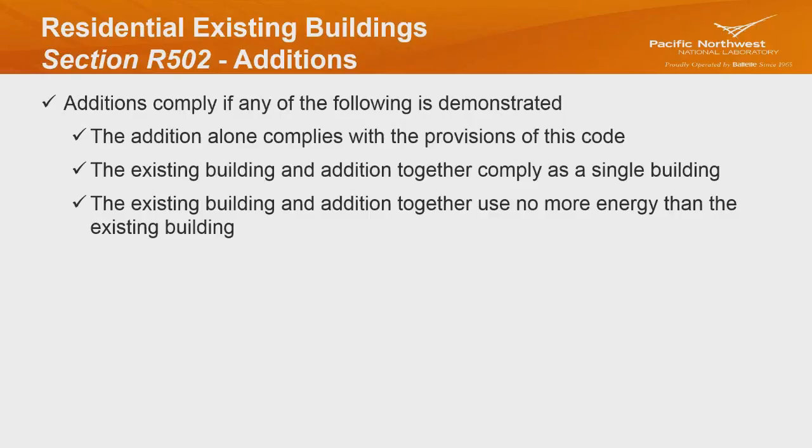And you're like, what? I don't get it. So the last bullet here is probably the most time consuming to figure out. Really what it's saying is, if I have an addition that I'm going to add to an existing building, and I'm going to run some simulations to see where my compliance is, as long as I'm not increasing the overall energy use of the existing building as it sits today, then I can comply that way. I don't typically see a lot of projects that way. They usually just try to show compliance to the addition alone, because it's the quickest and fastest way to do it.